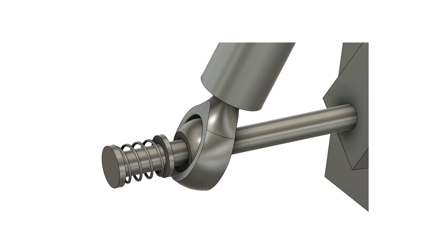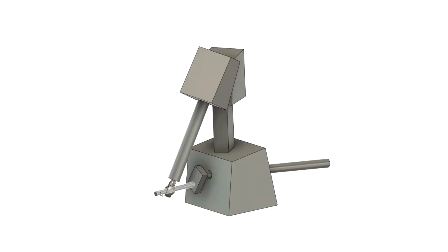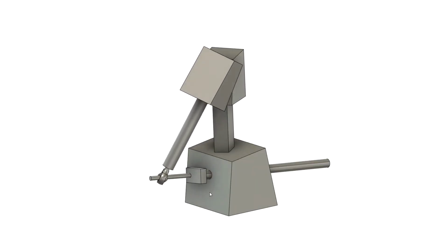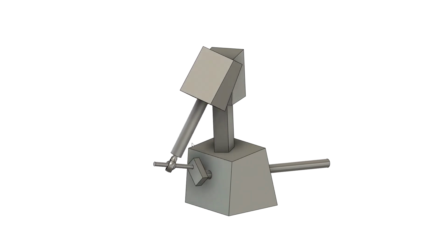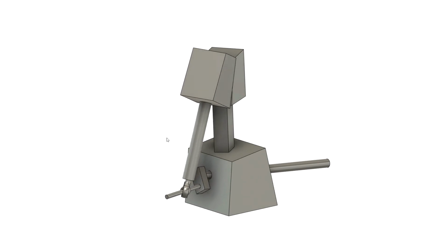A compression spring at the end of the crank pin, looking something like this, might be a substitute for the rubber band. There's still the question of whether an engine with much better fitting joints would work. Are those added degrees of freedom necessary for it to run? I don't know, but the CAD model suggests that this might not be a problem. Then again, the CAD model didn't predict the asymmetry of operation, the fact that Mark II will run only in the counterclockwise direction, nor the need for the rubber band.